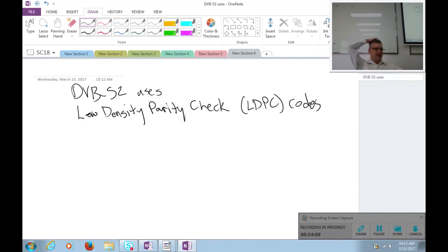But it's interesting in the world of coding theory, up until the 1990s, you pretty much had these same kind of codes available. There were these convolutional encoding techniques that people used. And then there was a whole family of block codes like Reed-Solomon, Bose, Chaudhuri, Hocquenghem. Nobody ever calls them that. They just call them BCH codes. And a family of codes that did a pretty good job, but were always about like 7 or 8 or 9 dB away from the Shannon channel capacity limit.